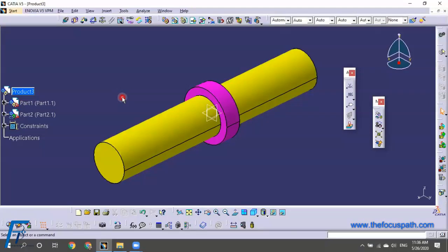Okay. Better, when it is for very specified dimensions or geometry, I would recommend use parameters, where number of instances, or you are going to use rectangular patterns or user defined patterns, something like that. I would recommend always use the parameters relationship. When it's mostly aesthetics or more of reference elements play an important part in terms of edges, faces or sketches, better always publish those geometry and use it.